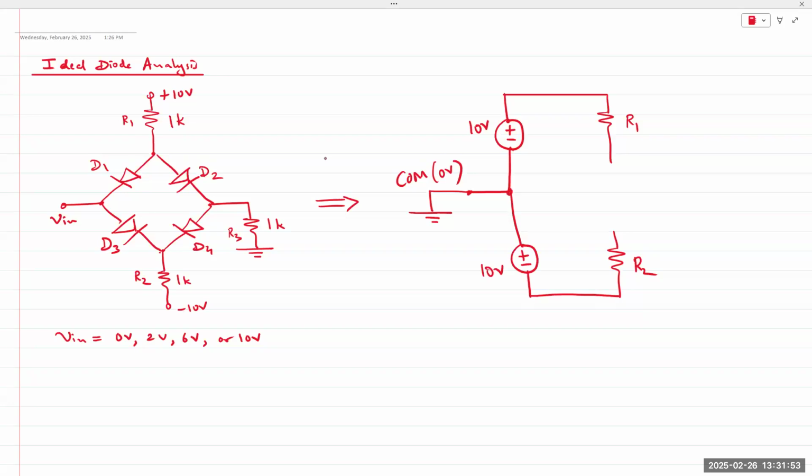And this is the dual power supply we created for our op amps. We take two power supplies, plus minus, plus minus. All we are doing is connecting the negative end of the first one to the positive end of the second one. So you're pushing the second power supply below the first one. So we get dual power supplies, plus minus. That's all it is. And so I always like to draw the circuit out in this manner.